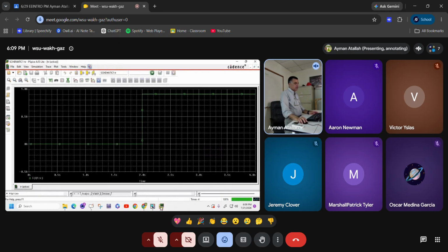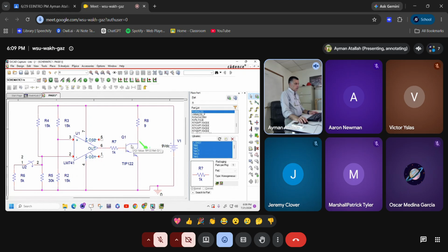So everybody got this? That resistor, you have R8 up there, is that just 9 ohms? 9 ohms, yeah. I make it low to represent the motor. The motor has low resistance. So I just want high current to be delivered to this resistor. So do the current marker again? Yeah, current marker, you can put it here. And this R8 here represents a motor.